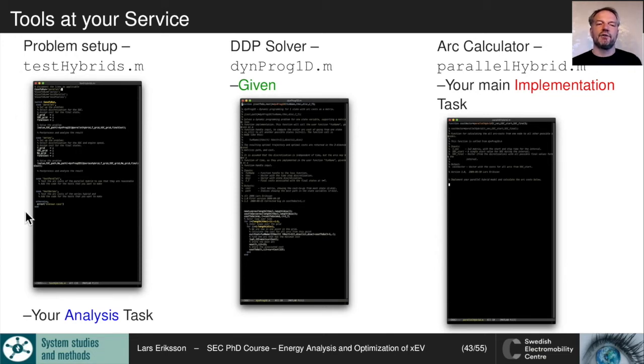One thing that we need to do is to pass values. For example, the driving cycle we will load in here, and the driving cycle will influence how much power requirement we have on the vehicle. So you will need to pass the information of the cycle to this function, and in this case we are doing it by using a global variable. So we define a global variable here that is the driving cycle velocity, and then we use the information about the velocity here. So this program will ask your program, you are standing in this time point and you are going to this time point.